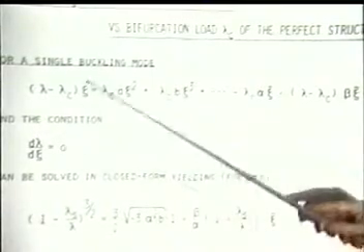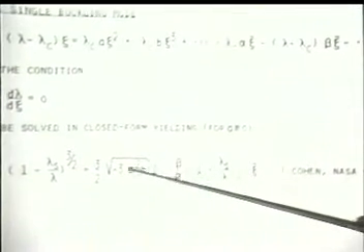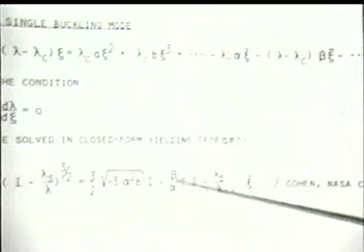If you want the limit point, at the limit point, d lambda over d xi c is 0. So you have two conditions, and combining these two, you can write the location of the limit point by this formula, which is essentially a modified form of Koiter's formula. Koiter has only done cases where beta and alpha were 1, so if you introduce here beta over alpha equal to 1, then that one cancels against this, and you have exactly Koiter's formula that he has published.